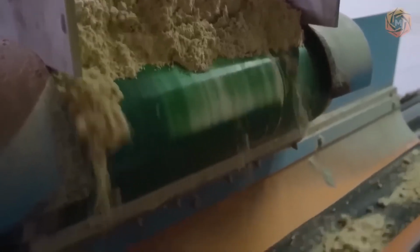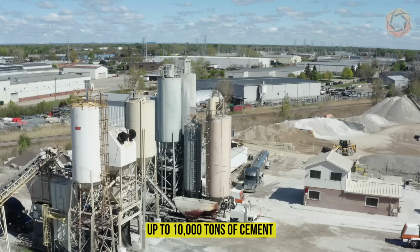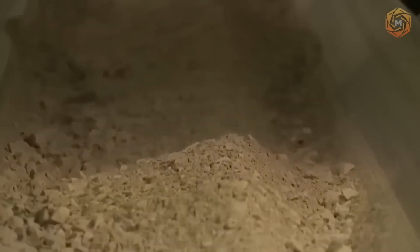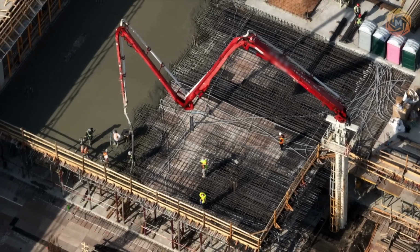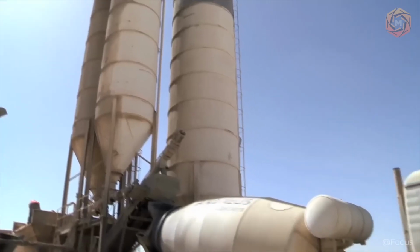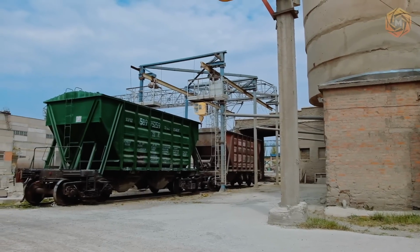After grinding, the resulting cement mixture is sent for storage in large reinforced concrete cans, or more simply silos. They hold quite a lot, up to 10,000 tons of cement. There it cools down a little at a time, and the residues of free calcium oxide contained in it are quenched by interaction with air moisture. Thanks to this process, the technological properties of the finished material are greatly improved. Afterward, from the silos, cement is shipped to consumers in cement wagons, auto cement wagons, and covered railroad cars.